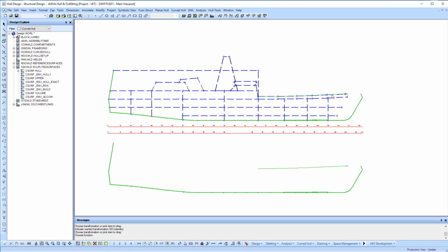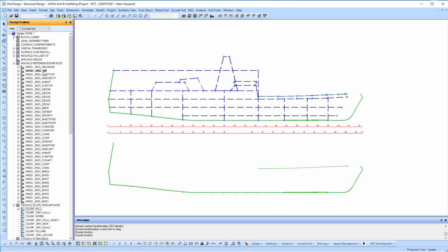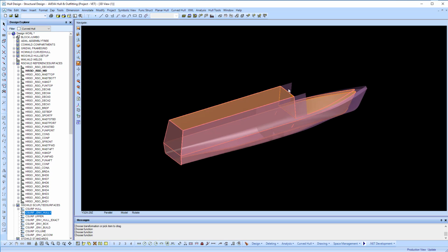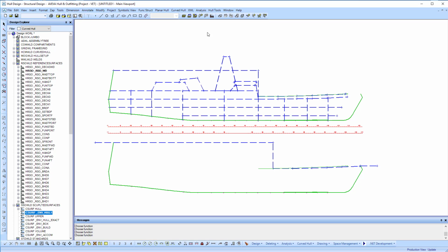So these surfaces would normally have to be updated by changing the definition, because it's quite detailed, the change in shape, where it should happen. But in this case, I've saved these changes to external files, so I don't have to spend time demoing that. So if I drag that change in, we can see that all the forward coordinates have been shifted forward by 5 meters, and this allows me to limit the envelope. So if we take a look at that envelope here, all we need to do is go and update it. So once saved, that envelope recalculates based on the new surface information.